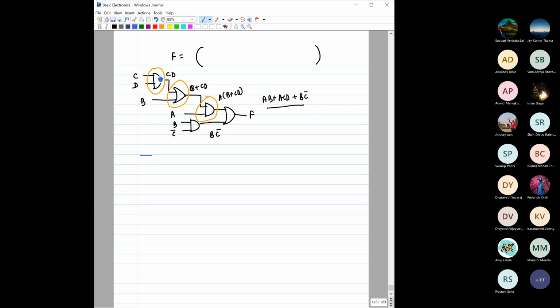So let us start. First it is this AND gate. The AND implementation, we know, is something like this: CD, followed by a NOT gate, which is the NAND equivalent. That gives you this AND gate. I can use this color to indicate that this was one of the gates.